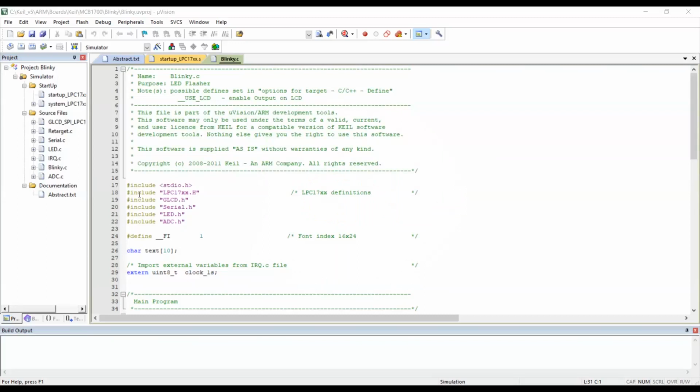First we will see the virtual registers. How do you see the virtual registers? As I told, they are for simulating your communication peripherals. Not all MCUs have the same set of communication peripherals. Some MCUs may not have I2C, some may not have SPI. So depending on the processor, the virtual registers are designed by the Keil team or ARM team. For this webinar demonstration, I have taken example projects. I have not developed anything separately. When you install the Keil software, you get all these examples by default.